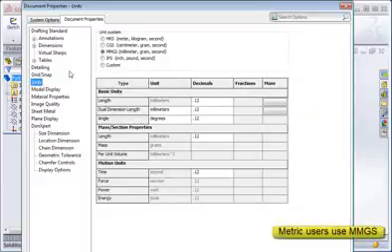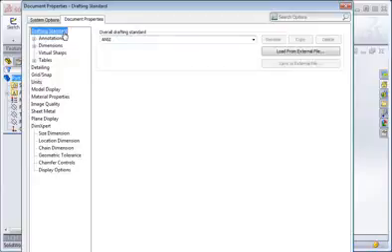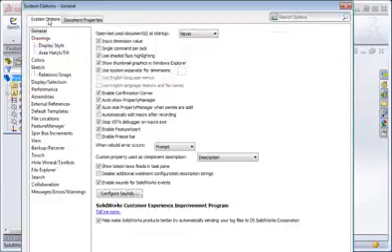Click Units and then change the default units for the file to inches, pounds, and seconds. We'll revisit these settings later in the course, but you might want to take a minute to browse through them. For now, we're just going to change the overall drafting standard and the units. Click the System Options tab, and here's where you can change settings that control the SolidWorks application.